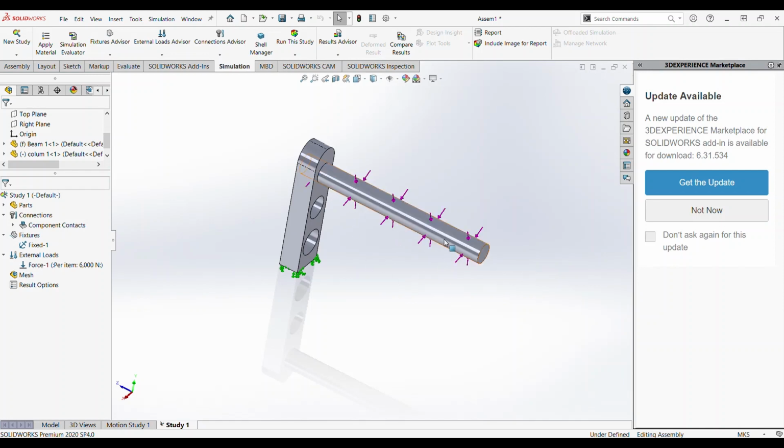So here we can select different materials for these two parts, or select similar materials for the two parts. To avoid complexity, we're going to select the same materials for these two parts. For selecting materials, we need to right click on the part, and you see apply materials to all.